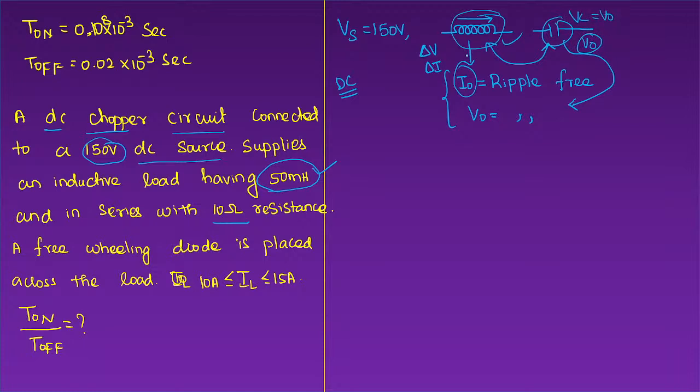If the inductor current is given, then that will differ by circuit, because the capacitor is always permanently connected in parallel to the voltage, but the inductor position will be different in each chopper circuit. In a step down chopper, it is placed at one point. In a step up chopper, its position is different. So based on the position of the inductor, the current flow through the output will differ.